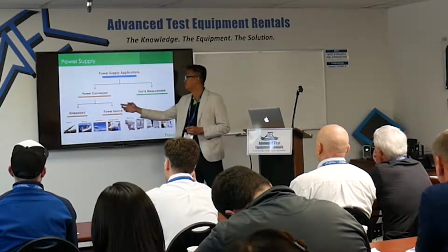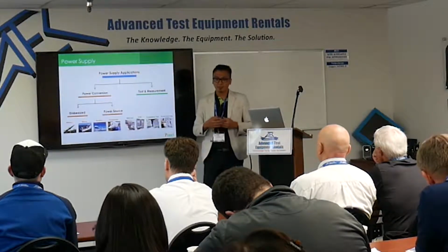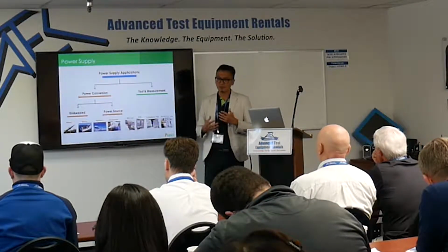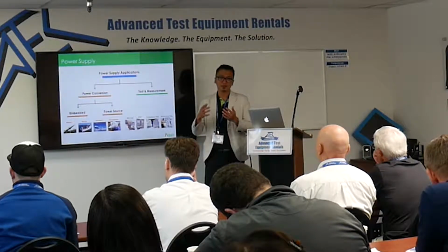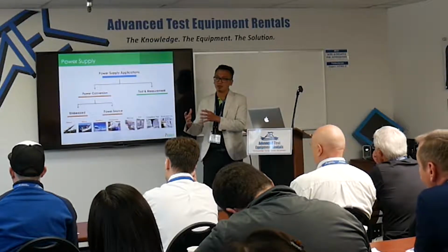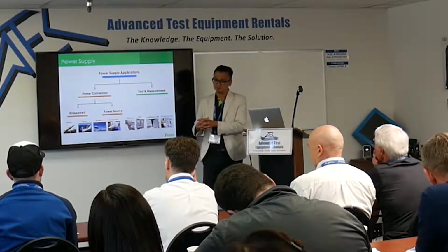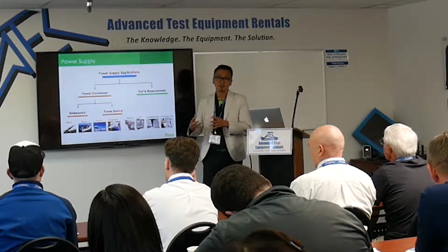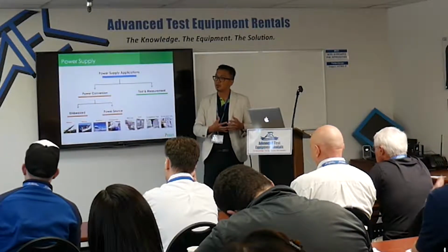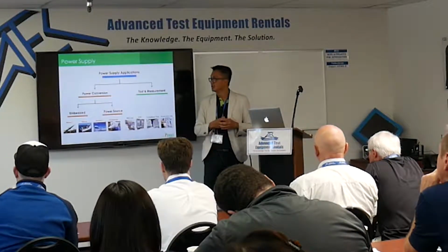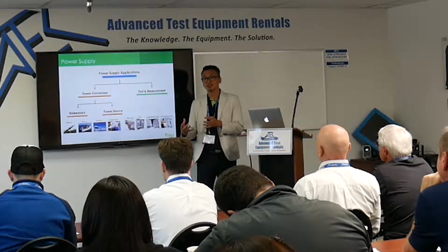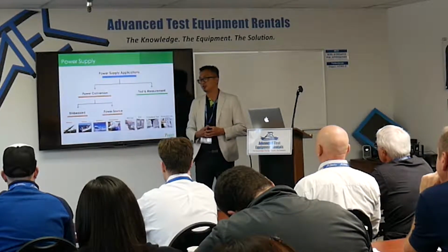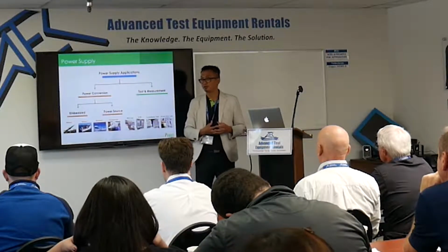Power conversion is a different matter. Usually for power conversion applications, you just convert from one voltage to another, for example 208 to 380 or 480. The frequency may be 60 hertz here, but the military needs 400 hertz, so you may convert from 60 to 400 hertz.